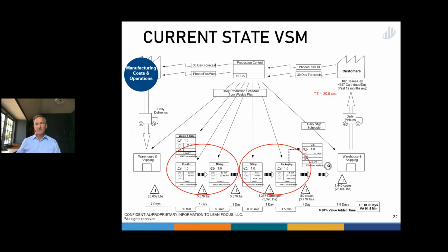So another thing we do is a value stream map, and a value stream map is a really good tool. It's very high level, so it's not a process map. It's kind of, we say, the 30,000 foot view. So you can just see the general landscape, but it really focuses on identifying bottlenecks, quality issues, machine uptime issues, looking for cycle time versus takt time requirements in areas of the plant. So each box could be many different steps in a cell or on a manufacturing line. If there's no handoffs, we just think of it as one process box.